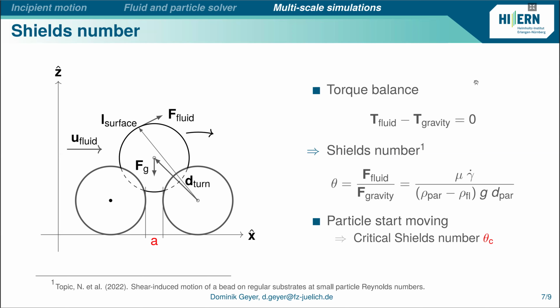So when the particle is moving over a lattice point which is not occupied anymore, we do the average about the mass of the fluid nodes. But you can also say, okay, I delete this fluid node, memorize the mass, and plug it in again. So I would say in my case, it's not completely mass conserved, but it should not matter. Yeah. And at the same time, you're releasing some on the other side. Yeah, I totally agree, but you can have the case.